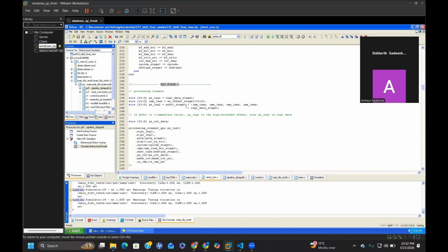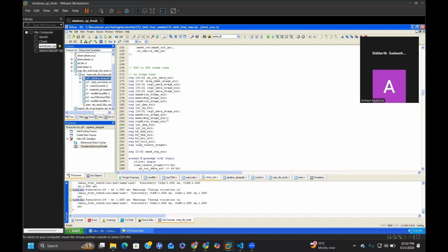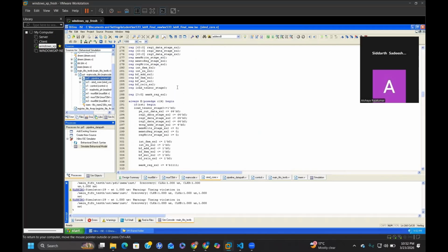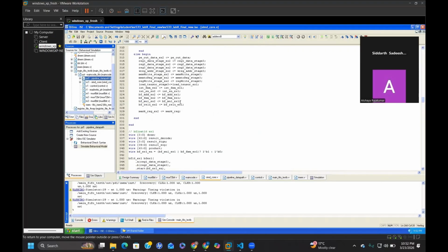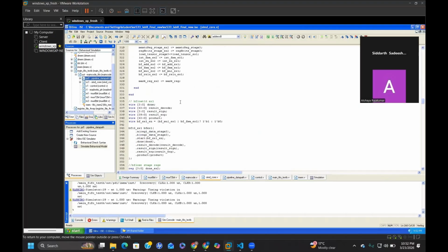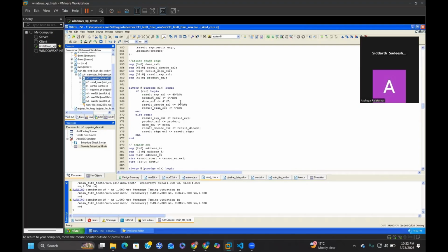Now we have the EX1 stage, where we have the processing element. This processing element has 4 instantiations of 16-bit processing elements. Basically, it has 2 execution stages for BFloat multiplication and 2 execution stages for BFloat addition. When an FMA is done, the data passes through all four stages so that the FMA can be done. If it's multiplication, it will be done in the first two stages, and if it's addition, it will be done in the last two stages.